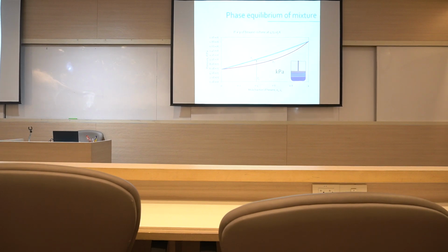Right. Then, if we keep pressing the piston into the cylinder, of course we hit bubble point. Okay, we hit bubble point here. So over there, the pressure is 1 megapascal. Okay, 1,000 kilopascal is basically 1 megapascal. That is bubble point. It means the system has just been compressed to entirely liquid. The liquid in this system is saturated liquid right now. Okay? When it is entirely liquid, X and Z are the same.